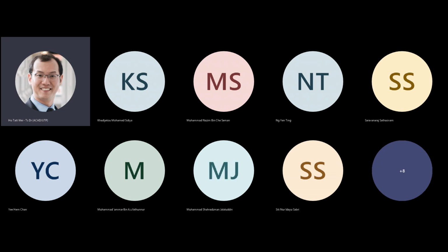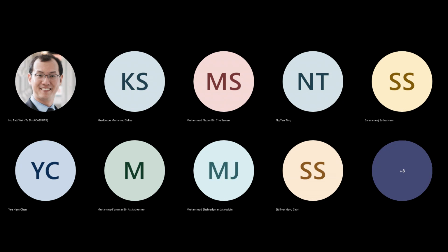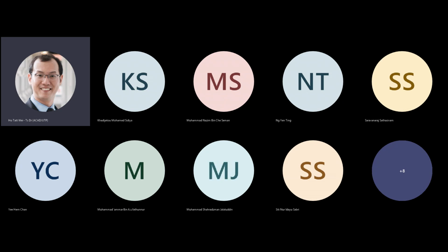This is a channel with a NOT gate, and this is a channel. So this will be I1 and this will be I0. I can read this output. This actually forms a multiplexer because when the control bit is set as logic 1, there's a channel forming here. Whatever logic value that I put in at this input will be passed to this output here.